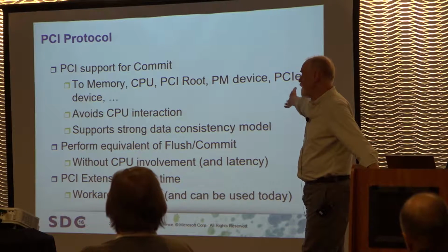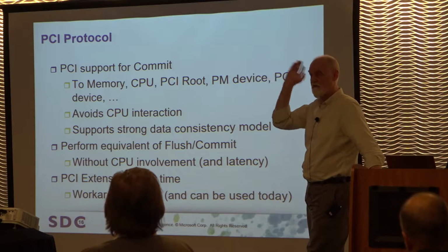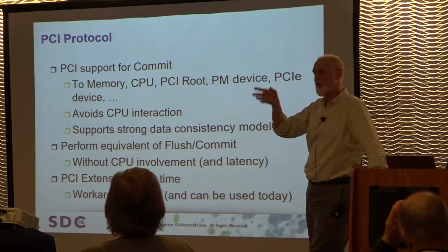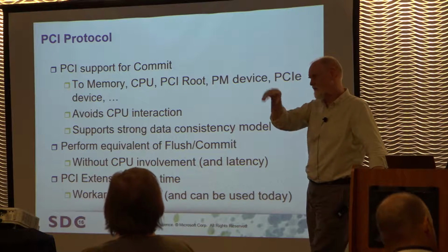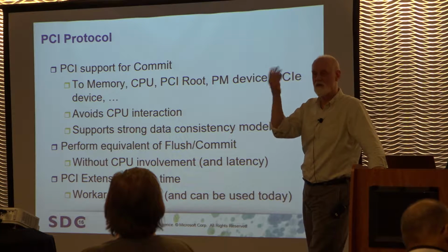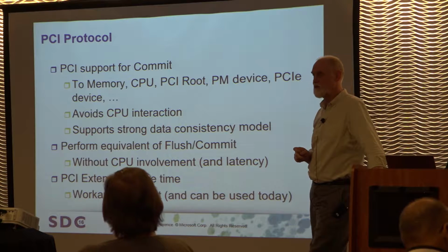And there's actually no PCI commit operation, right? PCI writes are fire and forget. They're called posted. You post the operation. It behaves just like an RDMA write. You post it, and some hardware accepts it to put it there. But there's no completion. There's no acknowledgement that the data actually arrived at the end completion on the PCI bus.